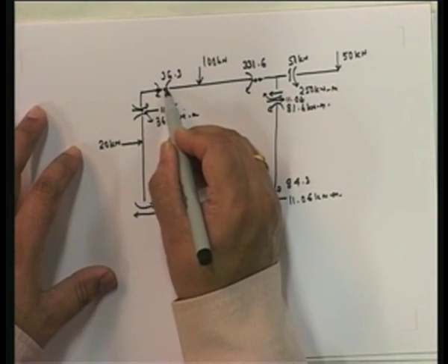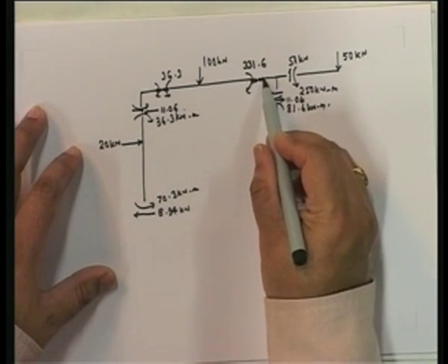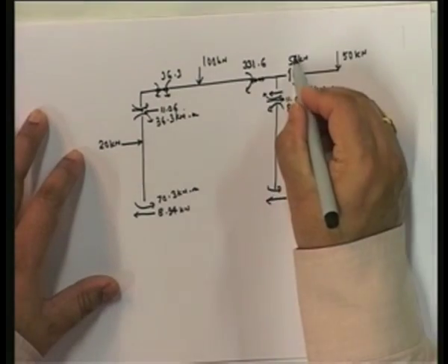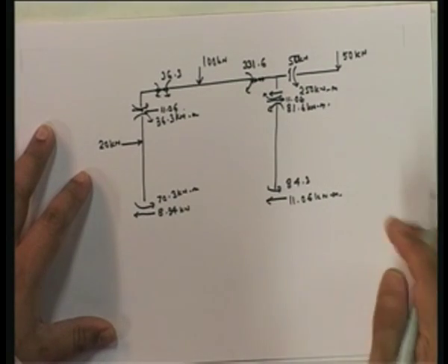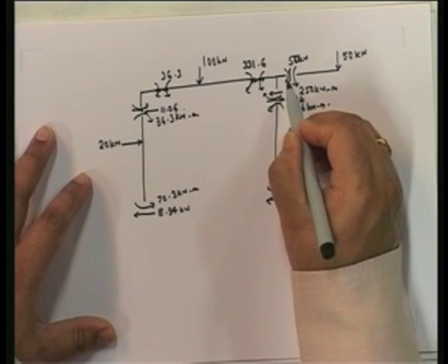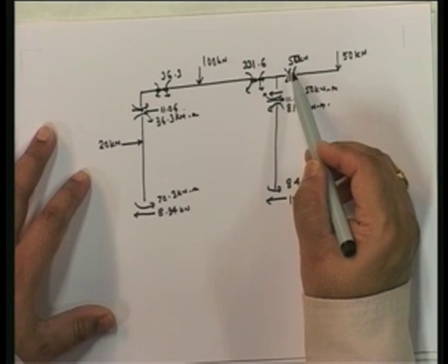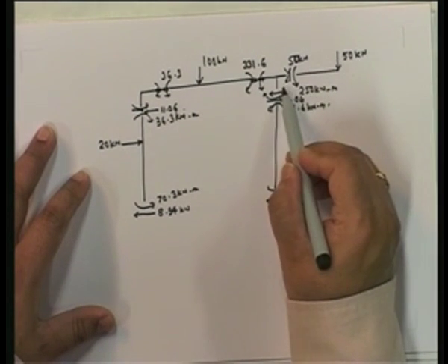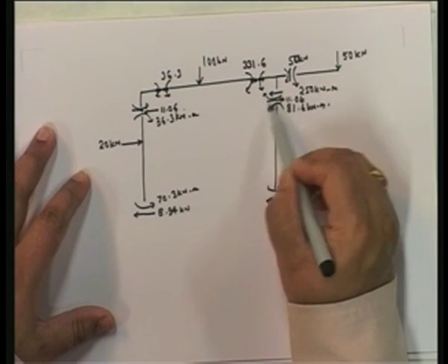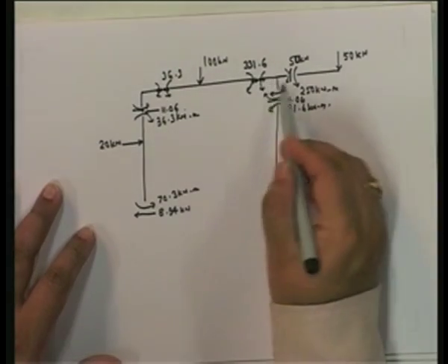Over here you'll have this, and over here just the opposite. This plus this 11.6 will give you net Fx equal to 0, which stands to reason. There's going to be this way, this way. Just check it out. This is 331, this is 50. This is 250 and 81.6. 250 plus 81.6 is 321.6, which is balanced. So there's moment balance, there's Fx balance.